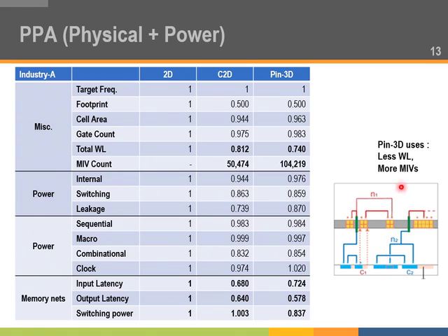So instead of routing through here, it uses one MIV to connect here, and then the wire can go through here and use another MIV to connect to the cell. So we have two MIVs on a net where it could only be routed with one MIV using an independent die-by-die routing. That is the reason we have almost 2 times the number of MIVs.